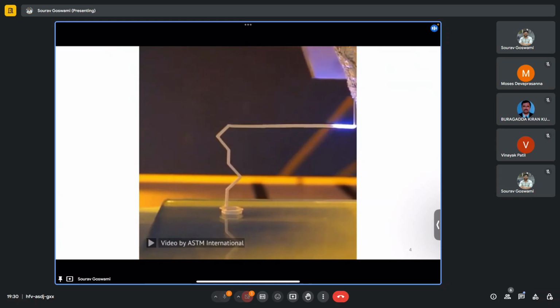This really shows the pace at which additive manufacturing technologies are growing and developing each day. So yeah, pretty spectacular. In case someone wants to find out more, this technology is called direct writing, and depending on the control of the chemistry of the filament material and the energy source, it is indeed possible to build overhanging structures in space with variable build directions, just like we were discussing. So the build direction need not be fixed along the positive or negative Z at all.